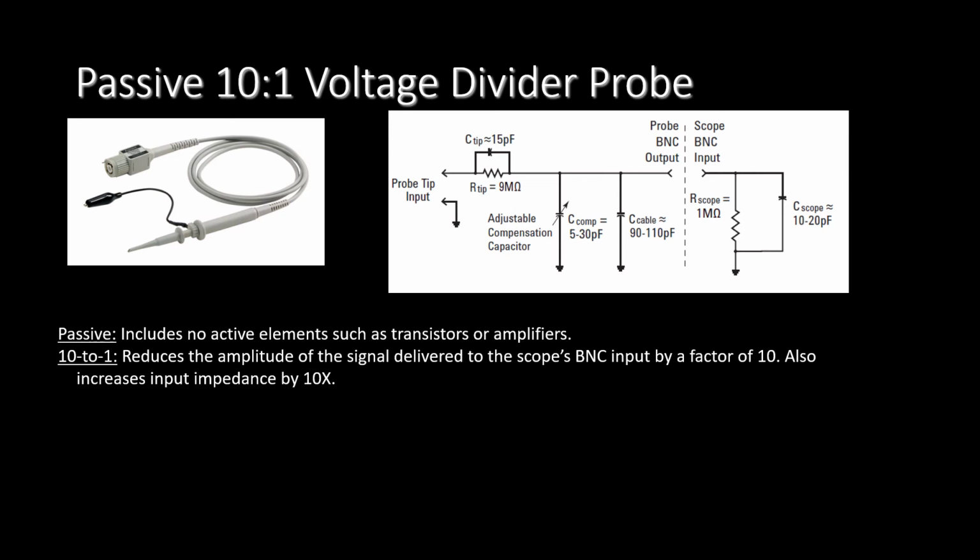Last, note that all the measurements using this type of probe must be performed relative to the ground. In simple words, you should connect the probe input tip to the desired test point, and you must connect the probe ground lead clip to a circuit ground. It is usually in a black color.